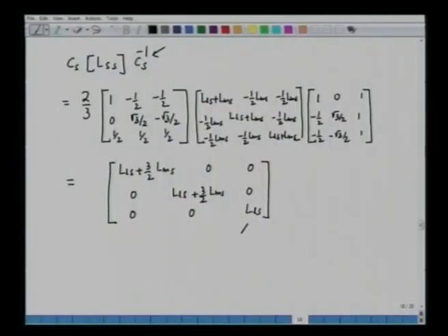And what is the zero sequence winding? The zero sequence winding does not have any coupling with D and Q axis. It can be assumed that it is a winding in the Z direction or in a plane perpendicular to the plane of the slide. Okay? So, we can think like that, that this is the zero sequence inductance. This is the inductance of the q axis stator. So, we can call this to be Qs, this is Os, and what about this? This is the inductance of the d axis stator, that is LDS.